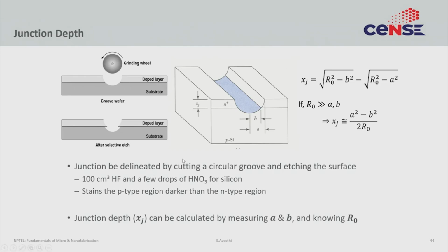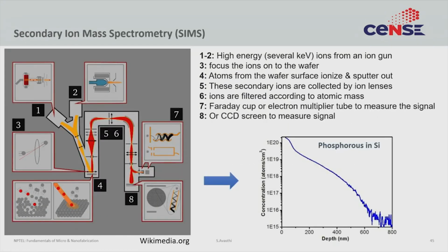So what you would see, looking from the top, is a component of this thickness. A component of this thickness looking from the top. So you would see some strips, but the thickness of those strips can be geometrically related to the depth. So using some simple geometry, you could actually back calculate what is the depth xj of this layer and give you doping thickness. I think the idea is really cool, but as I said, practically of limited use today. If you want to do this experiment, you just do SIMS.